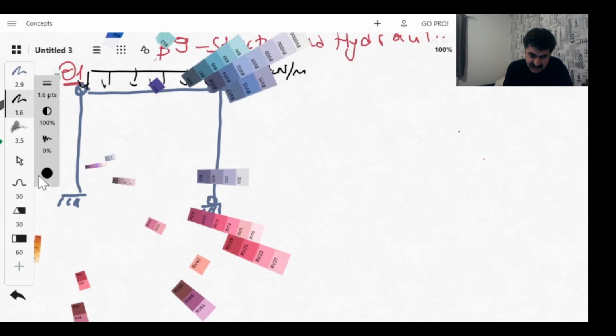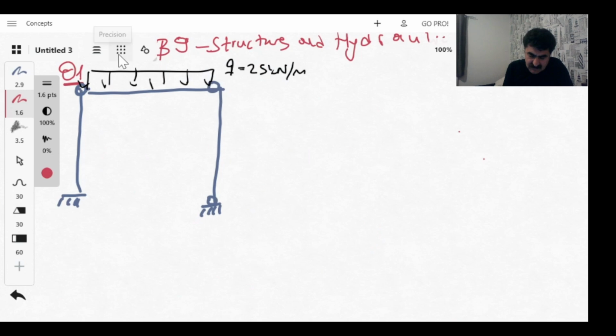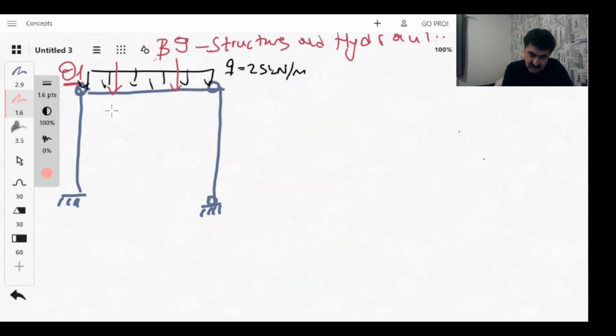And also we have point loads, and the point loads are machinery. Machinery should also be considered as a live load, because it may change always, and for the snow also, the amount of loads and the places of loads always change. So we consider this as a live load. It's changing, so the amount of the load may change as well.